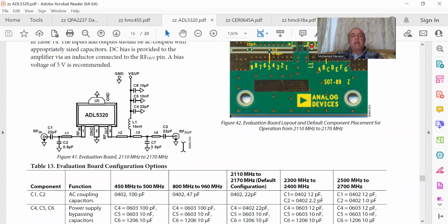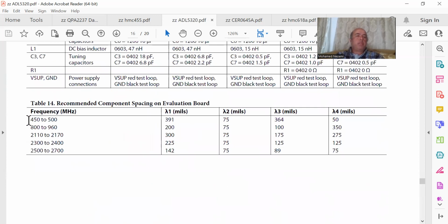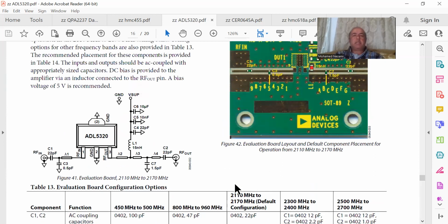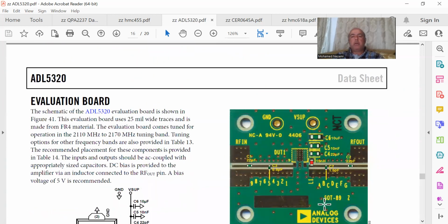ADS, and I put all of these in, and we run it through the optimizer just to make sure. Because for these bands that they give you here, for instance, we don't see one for the 15 to 17, as you can see. Which means that we can't really use any of these. You could use the closest, somewhere between these two. However, you really need to verify it, and we have to do that in ADS. In the coming videos that I will do, we will demonstrate how you do that.